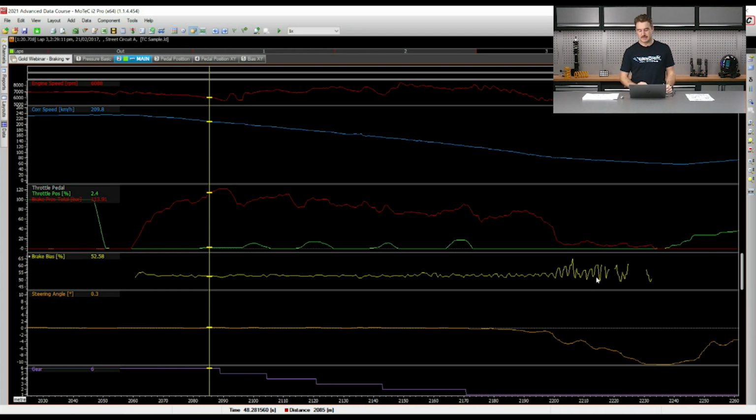Now, it's natural to get more bias variation at low pressure, so you're going to see it predominantly more at brake pressure release than during the main braking event. But it's also important to realize that in some cases people actually use this to their advantage, having different mechanisms in their pedal box to actually bias their brake pressure towards the rear axle on brake pressure release.